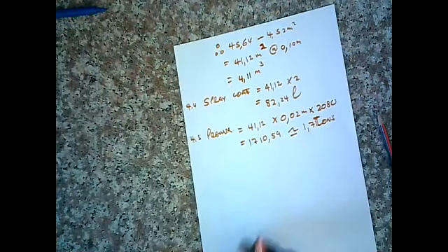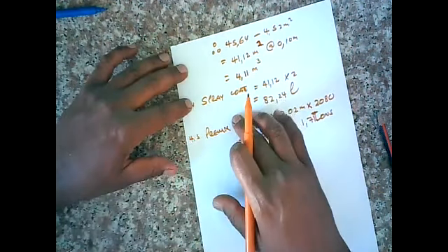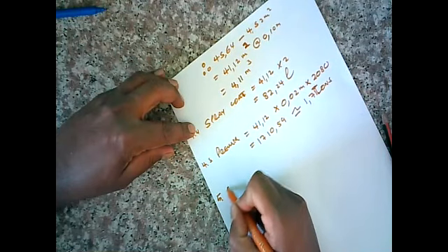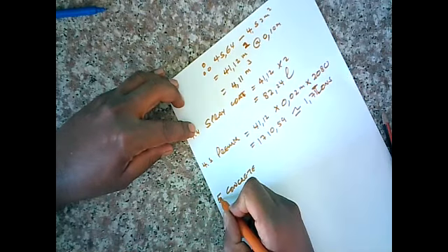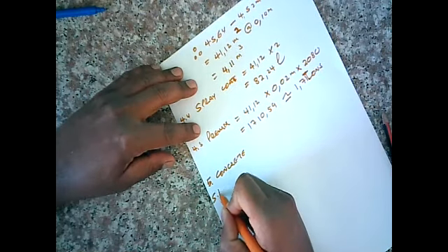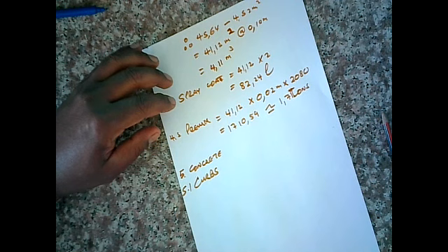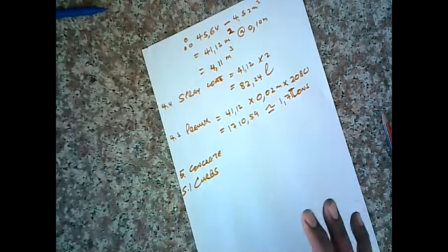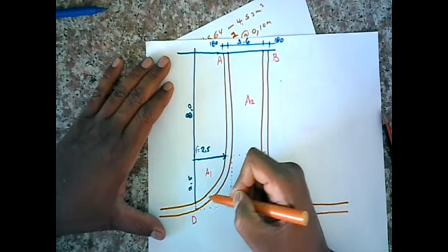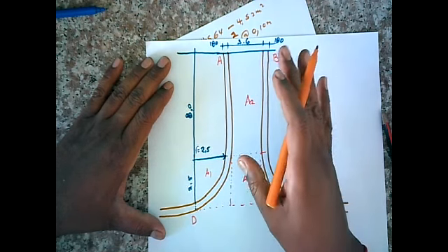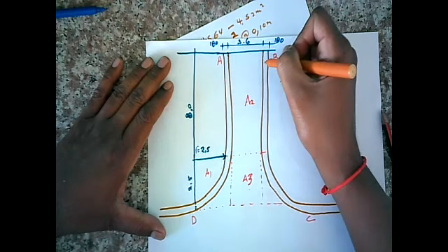All right, now we're finished with all the labels. Let's move on to the last item. Let's call it concrete. Now carefully here, do not draw on your knowledge from concrete quantities. All right, and let's call it curbs. And what are we trying to find here? We're trying to find the length. Remember the unit in the notes, it said meter. We're trying to find the length from here to here times 2 for both sides.